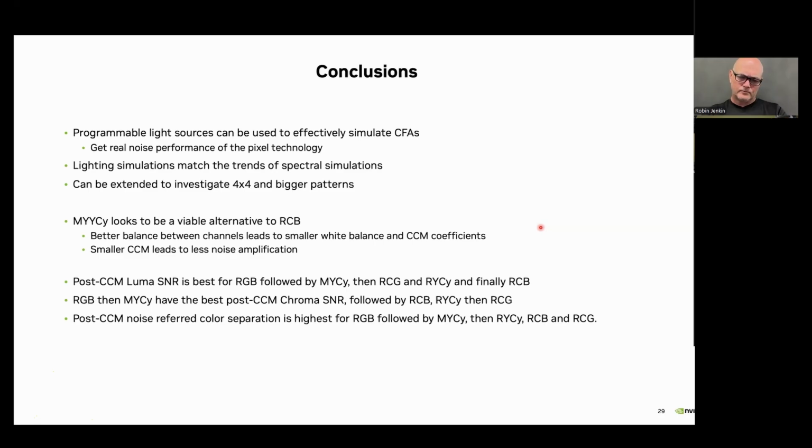Our rods have linear response and they saturate when we go outside. Our cones are effectively a log response and they're the HDR part of our imager. I mean, our cones are, so they give you the color. Have you looked at two imagers side by side, one being a larger pixel monochrome for doing the night, and a second camera next to it that's an HDR imager for the color? Then at night you average the color in low light situations and superimpose it on the luminance channel that you get from the monochrome.